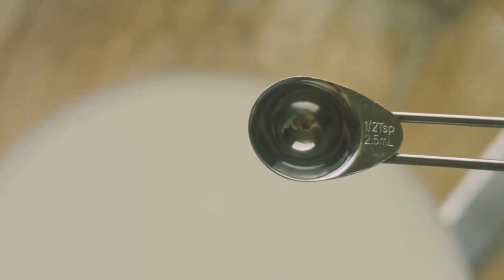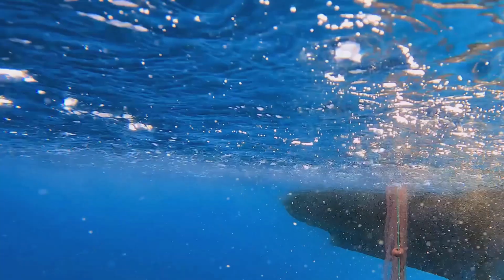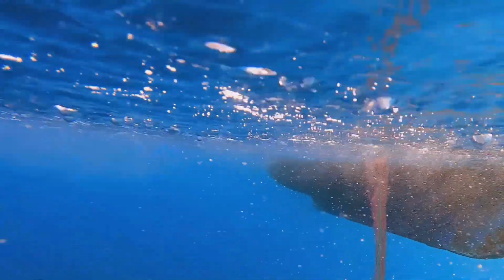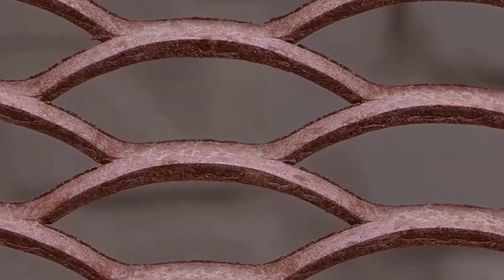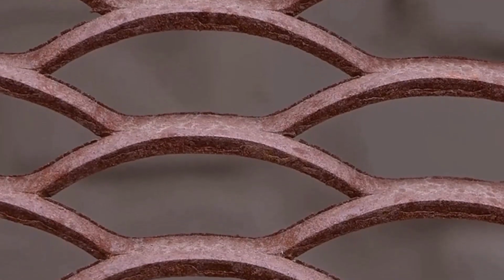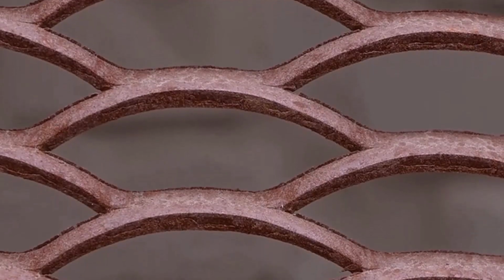Essentially, Y+ is the secret ingredient for our simulation recipe. It's a normalized distance that tells us how fine our computational mesh, or grid, is near a surface. Think of the mesh as a fishing net that we cast over our object to capture the fluid's behavior. If the holes in the net are too big right next to the surface, we'll miss all the important details happening in that slow, sticky boundary layer. Y+ helps us make sure our net has tiny, fine holes exactly where we need them the most, right up against the wall.